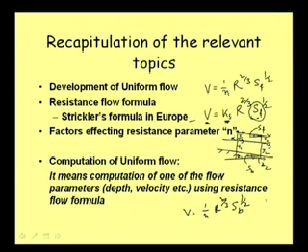Why am I emphasizing this point? Because when we will be dealing with non-uniform flow, like gradually varied flow, then also for some situations we approximate the small channel reach as uniform, though the entire flow reach is non-uniform, and in those portions we consider that the uniform flow formula is valid. But in that case we cannot use SB, we will have to use SF. So, that is why these sorts of finer points we need to be careful about.